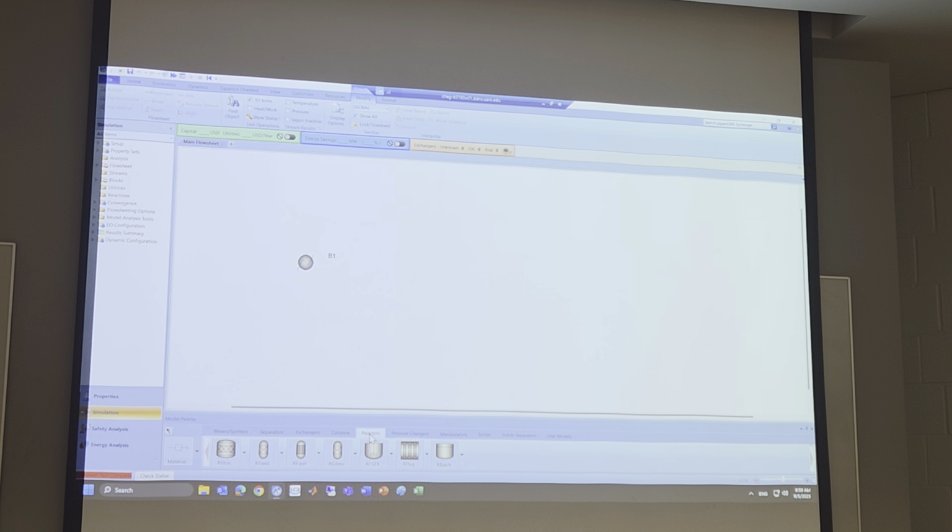And then if you go to reactor, okay, we are familiar. We use the R-Stoic reactor today. When I say step by step, just learn up to here. Always, the reactor is a very important unit block or unit operation. So learn up to here, make sure everything works. So let's go step by step. We have 2 feed streams. Okay, H2 feed stream, hydrogen, and we have the benzene feed stream.